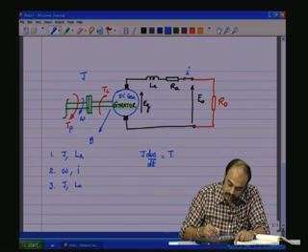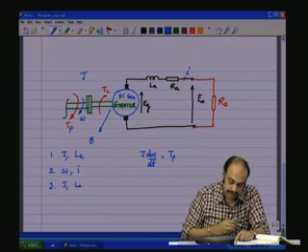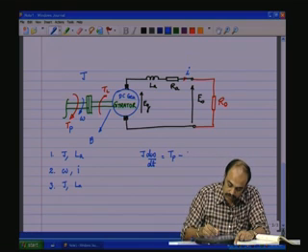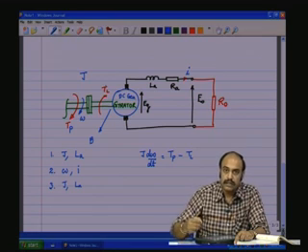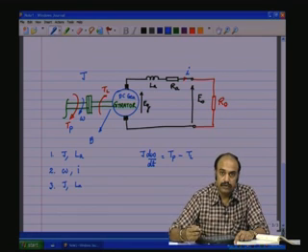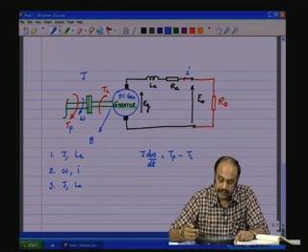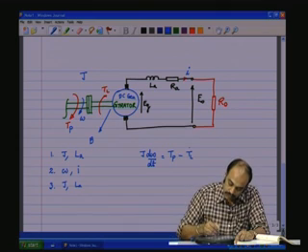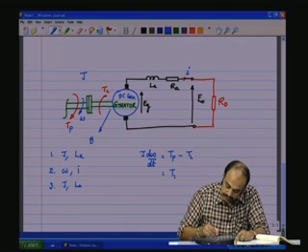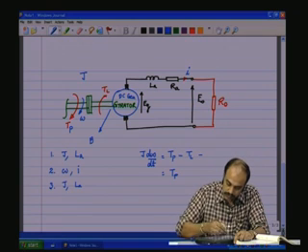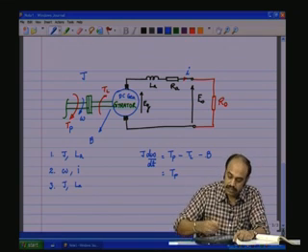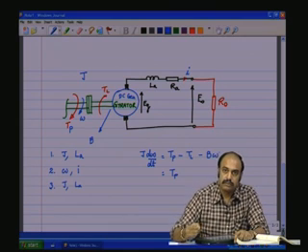the torque that is produced by the prime mover, Tp, minus the load torque for the prime mover, which is actually the Lorentz torque reflected from the electrical side. There is also a friction element, B. Friction is a dissipative element acting on the flow, which is minus B omega.